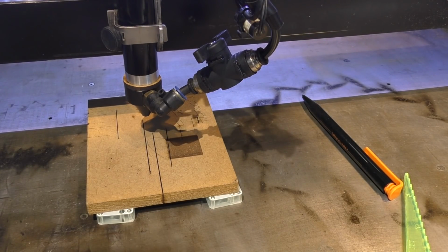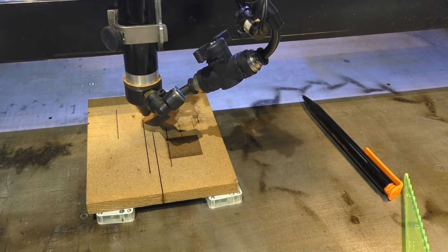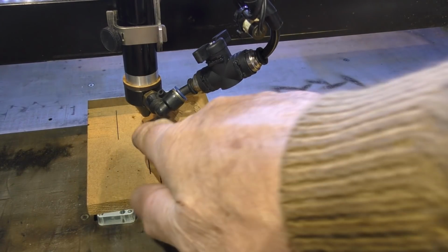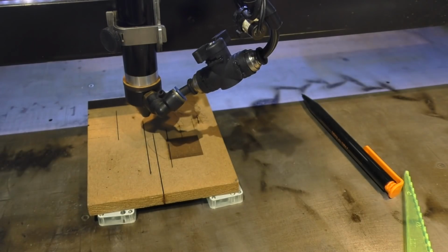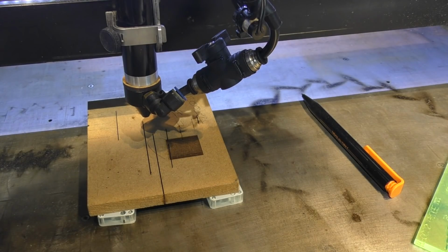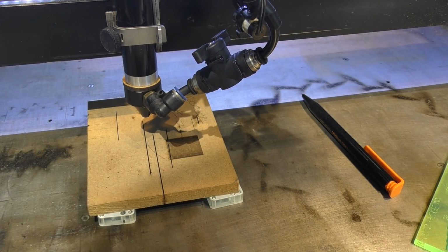Now, this pump, this compressor is supposed to be able to work with something like about 150 litres a minute. Now that's 20 times more than what I'm putting through here. But of course, that 150 litres a minute is 150 litres of uncompressed air. This little compressor, it's not small, as you can see, is struggling to keep up with even that low flow.